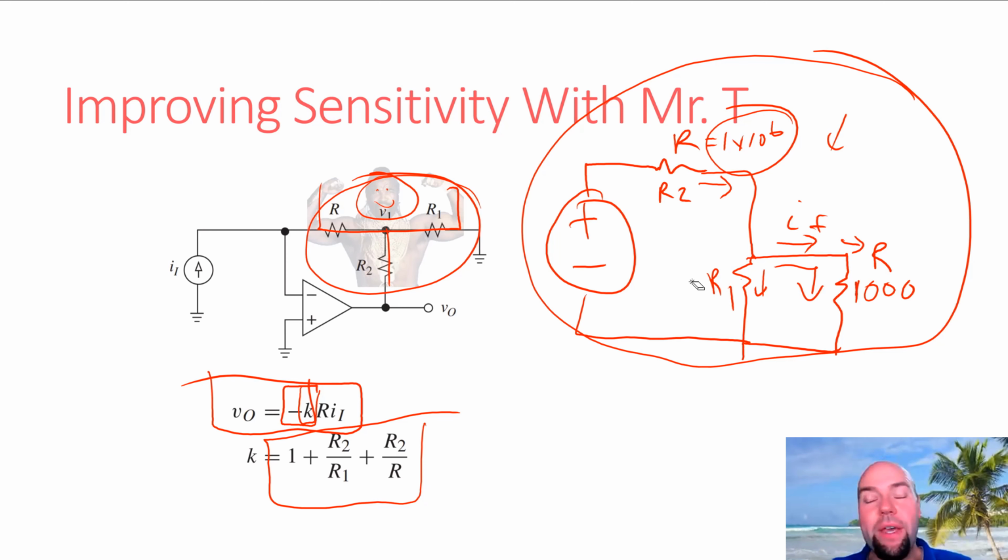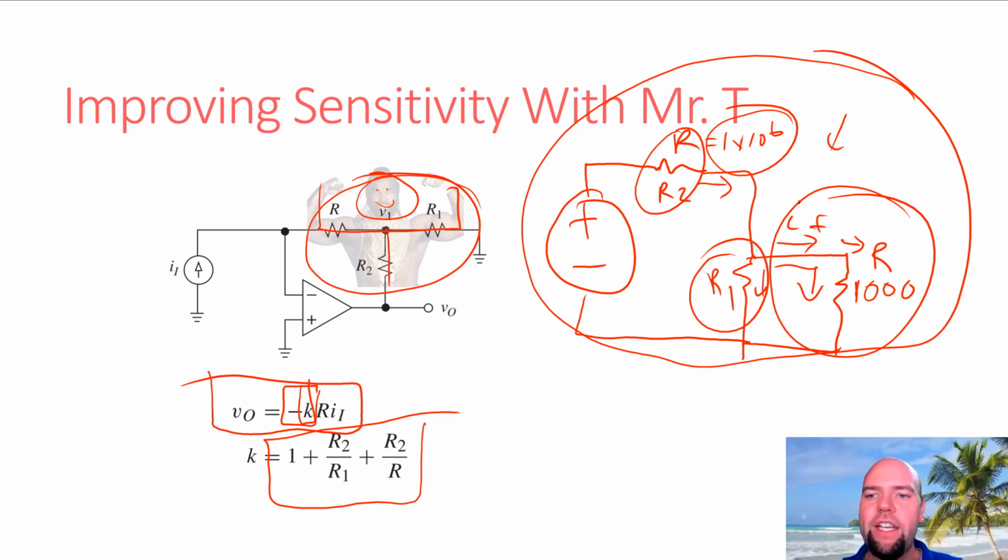Another way to think about this, by the way, is we produce a voltage divider between this resistor and this resistor. So we divide the voltage with a voltage divider, and then we convert that voltage to a current using a resistance R, which is mathematically the way the R's are represented here. You can think about it either way. It's two ways of choking the feedback current.